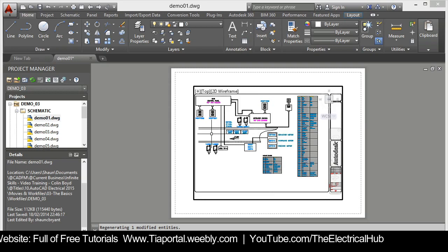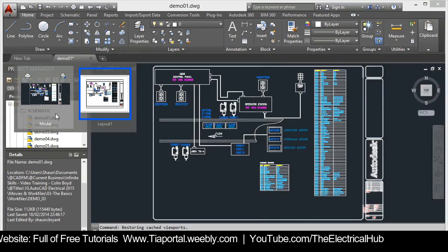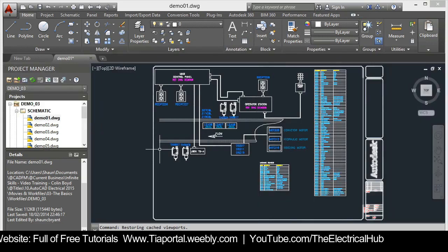How do I get back to the model space? Well, I can do that very easily. I can just click on the button here and you can see, look, that toggles. There's paper and there's model, like so. But it leaves that current view as the view that you last used. So even though that says model, I'm not actually in the model space itself. What I can do is hover over the tab, go back to the model tab in the drawing here, and that takes me back. So you can see there's some tools there on the status bar. They're all about assisting you in working in AutoCAD Electrical. So make sure that you familiarize yourself with your status bar in AutoCAD so that you can work effectively and productively when creating your electrical drawings.